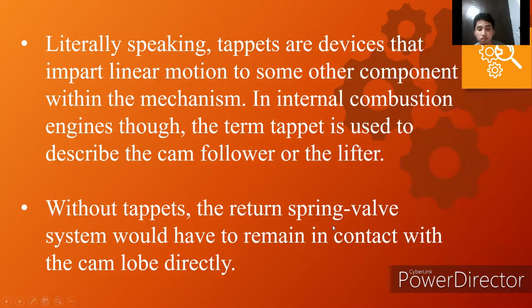Without tappets, the return spring valve system would have to remain in contact with the cam lobe directly. So, kung wala akong tappets, yung valve spring na nakakonekta sa rocker arm na nakakonekta sa valve is nakakonekta mismo diretso sa camshaft, which is dapat iniiwasan natin.